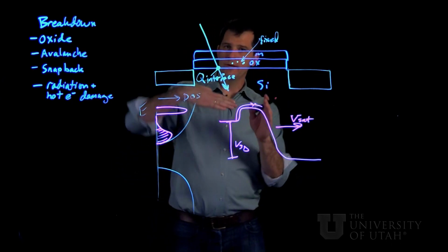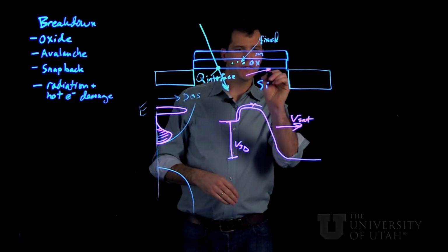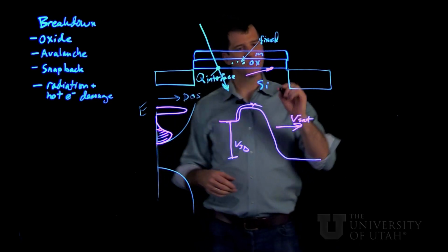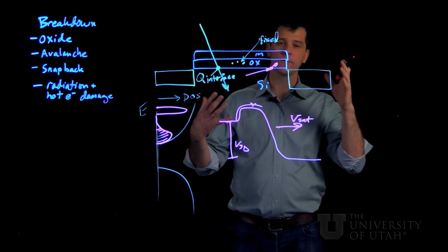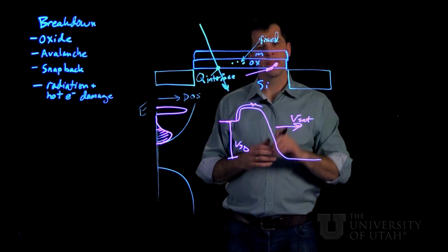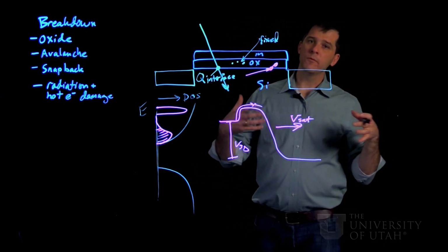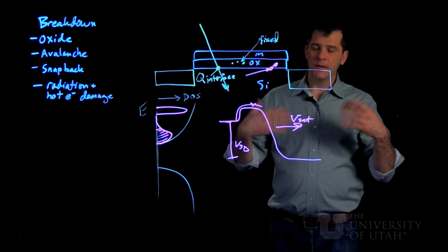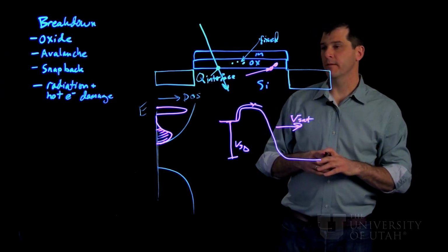And that means if they're going past this oxide interface, there's a chance that they'll actually run into atoms at that interface. And when they do this, they have enough kinetic energy to actually move that atom off of its perfect lattice site, or its perfect bonding site, and actually create interface charge. So this form of damage could be considered a form of internal ionizing radiation in a sense.